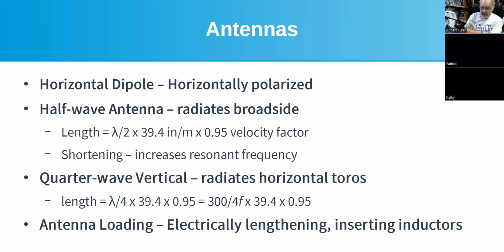Of course, when you do that, you better add some extra length, because even though your calculations might be down to 4 decimal points, because other things affect it, your answer is not going to be right. So if you're not resonant where you think you're supposed to be, then you have to adjust the length of the wire.